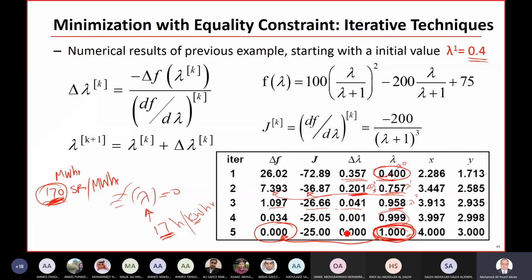This is the same as the voltage at each bus, nominal 1 per unit. Exactly, this is also the case for the load flow problem. In solving the load flow problem, you expect the voltage to be around 1 per unit, so you can also start with voltage equal to 1 per unit. So this is the wise start. But of course, we do not start with voltage equal to 0.2. This is unreasonable.